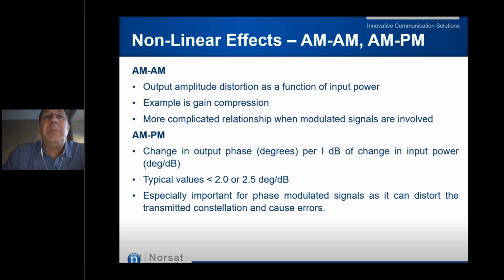And this is especially important in phase modulated signals, where the phase error, the phase change, can start to degrade or distort the transmitted constellation, and can lead to or help cause some additional bit errors.